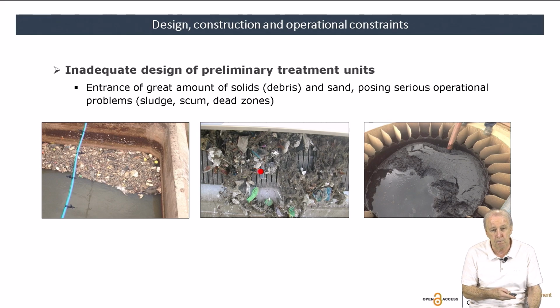And we know that many sewage treatment plants only have coarse, maybe fine screens, but not sieves. So sieves become one important structure to be planned and designed to avoid this material going into the reactor.